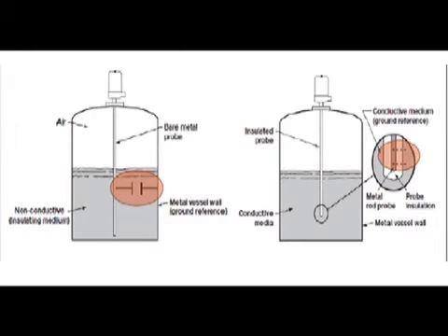Take note here, if the medium is non-conductive, then it provides a large change in the dielectric constant. If the medium is conductive, then an insulated probe is used and the capacitor is formed by the outer surface of the insulation to the wall and the electrode.